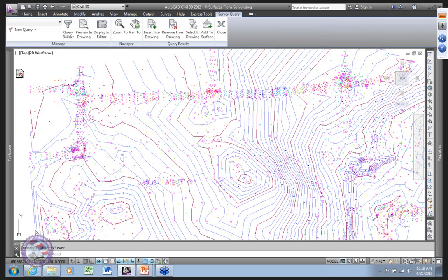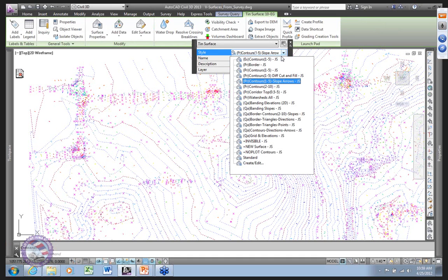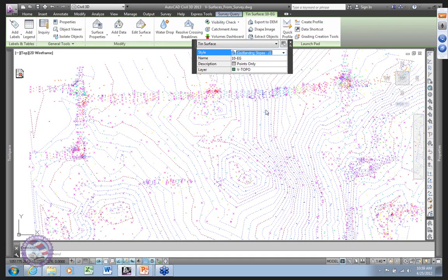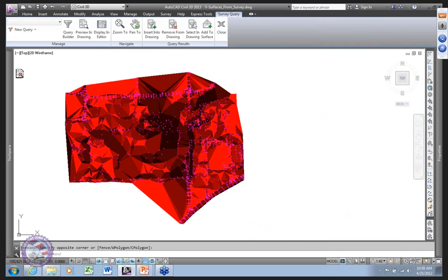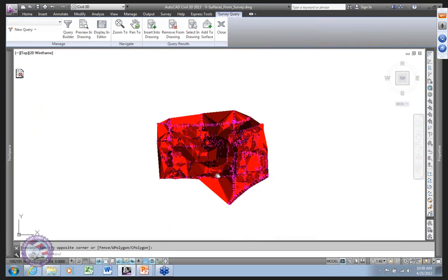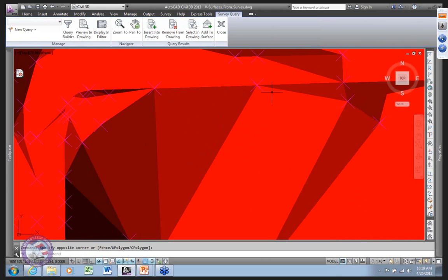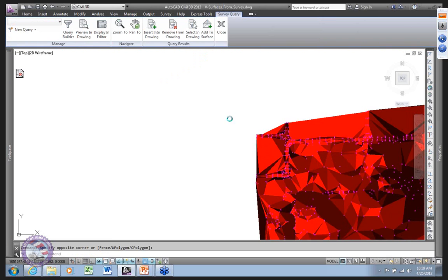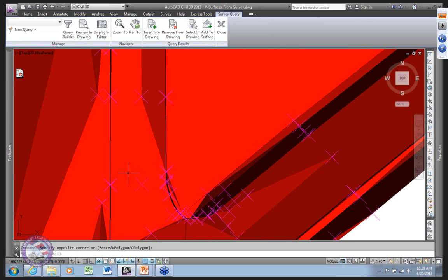We got our surface, okay? We wanted to grab that surface thing again. We wanted to change it to another way to display this, banded slopes. Okay, and what this effectively means, being visually, is the blacker it is, the steeper it is. Okay, so that also gives me a way to, okay, so you can see no curb and gutter. Right. Down here, we got ditches. Okay, little bits, really thin lines of black, steep stuff.